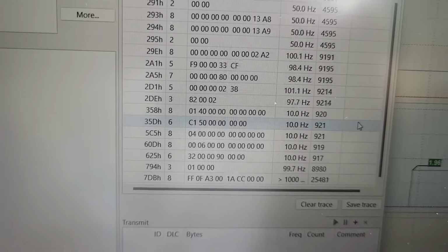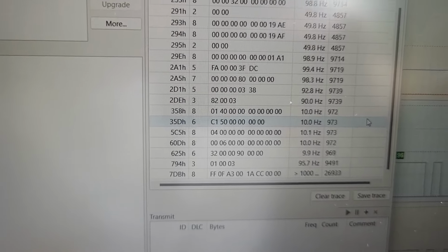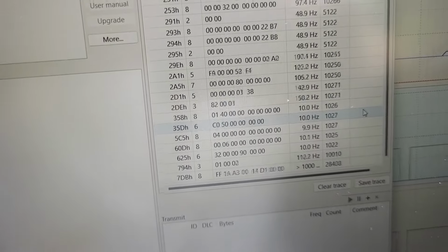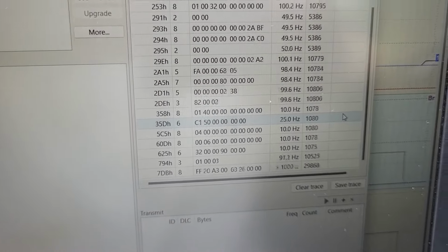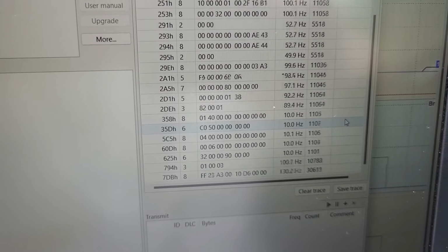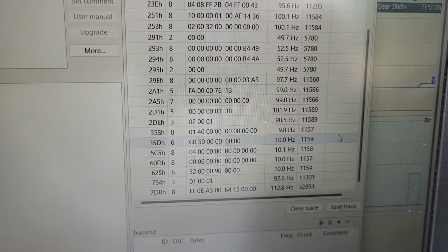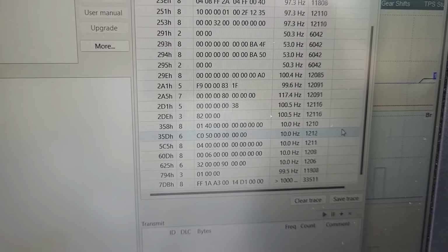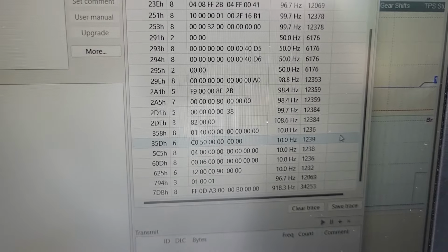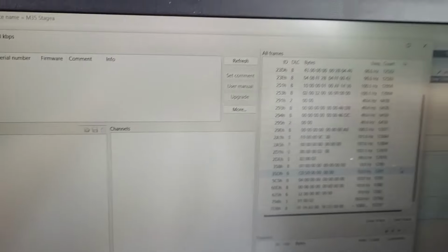The update is 10 hertz, so not very often. That's for the body control module. It's not mission critical stuff. Some of this other stuff will be live data, engine parameters, key things. So we've now found our message, and we've found that when that byte goes to C1, that's what we're going to be plugging into our ECU Master software to hopefully figure that out. Cool, right, I'm going to turn this off and jump back to the slides.